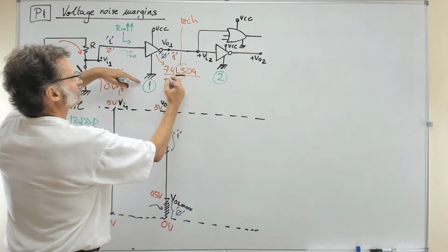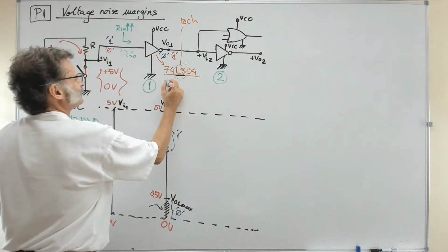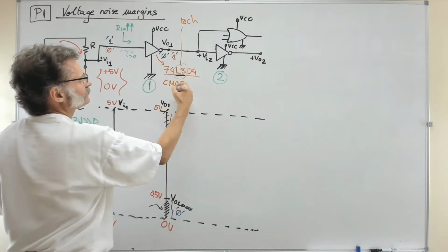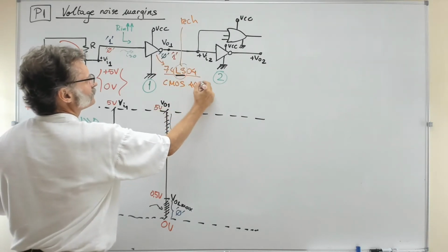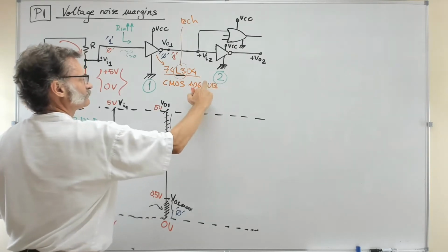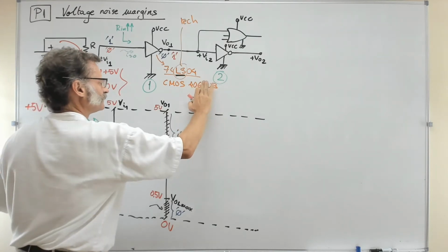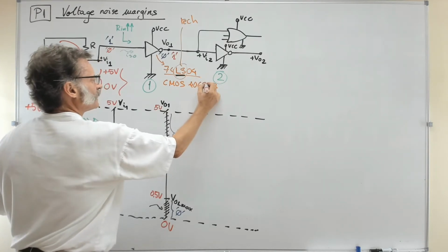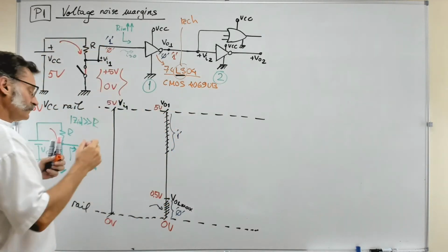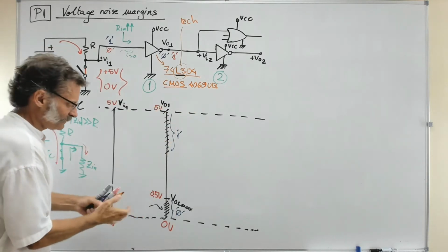If you pick up another one, for example, I don't know, the series CMOS equivalent circuit, like this is the CMOS 4069 UB. There's more lettering here, but it doesn't matter. The reference is the 69. 4069 is the same thing, a sextuple not. But it's another technology, so I mean that here you have different values.